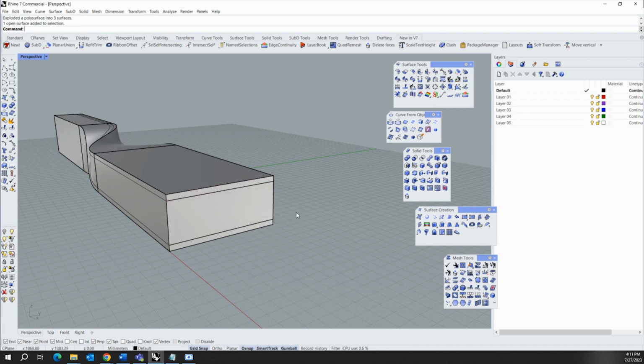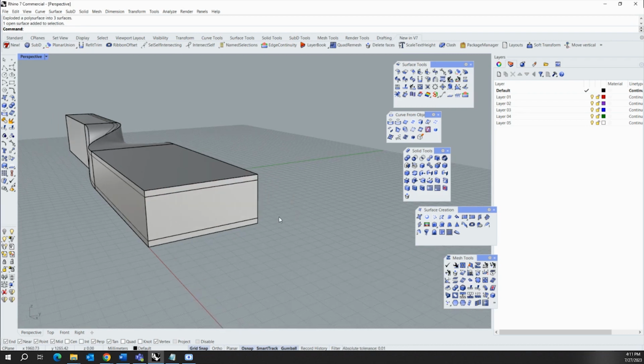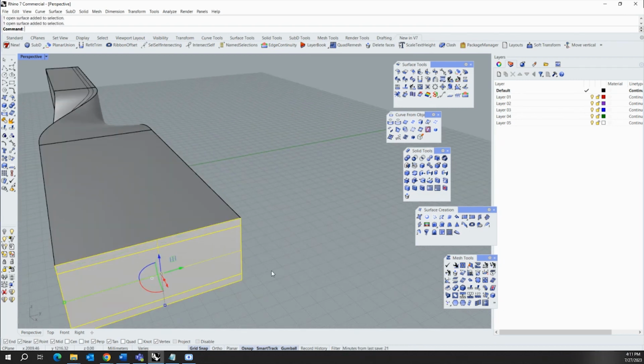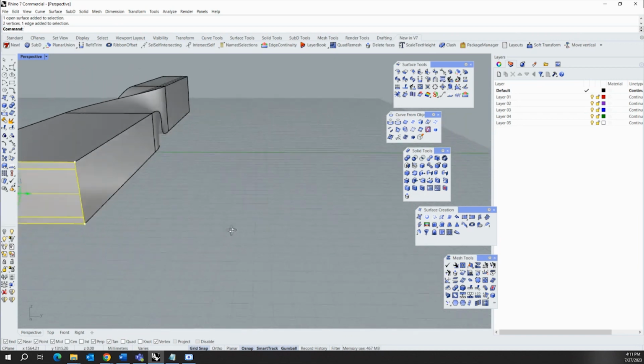Then you can hold shift control and use left click so that it selects the vertices. You need to move these vertices by 100, right? So you have to select these three surfaces, shift control and select this thing. So it will be selecting these vertices.